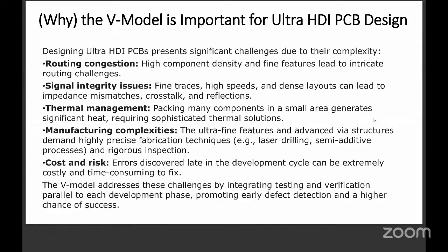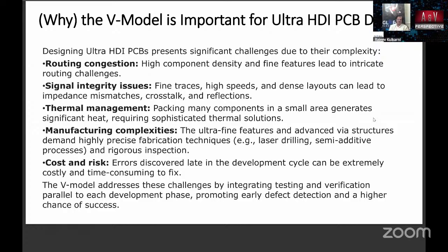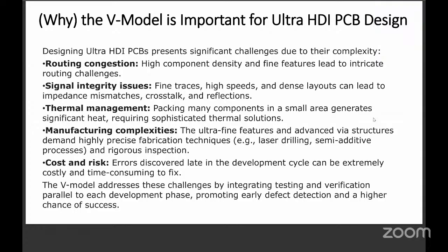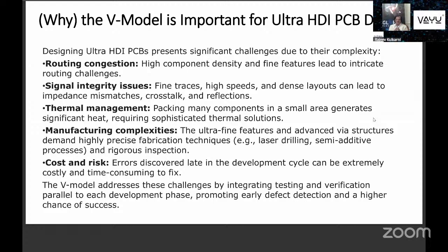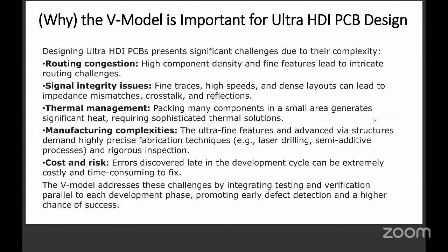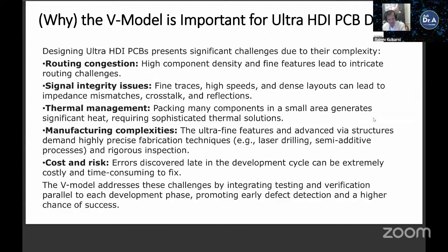Okay, insulated metal sheets. And what about liquid dispensing materials like silicone, like gap fillers? Yeah, they come in between the actual chip and layer one or the bottom layer of the substrate. It is also very much important. Cleaning is also very important in advanced packaging. Yeah, cleaning, encapsulation. If your encapsulation can also act as a thermal solution, it is very great, all rolled into one.